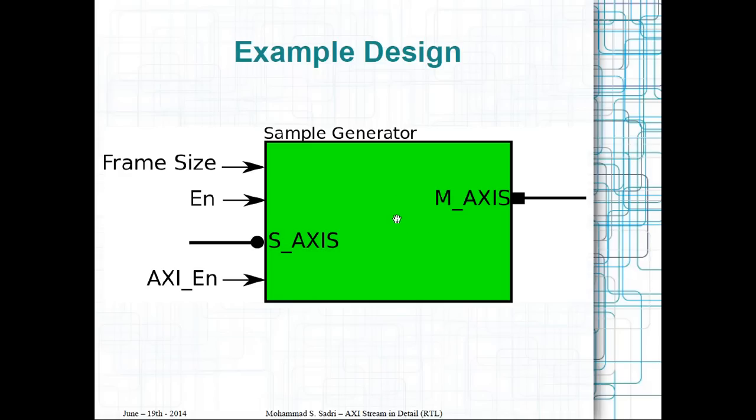first synthesize this block, because when you do an initial synthesis, usually it is useful because it shows you your major problems. For example, sometimes you do an initial synthesis and you see a large part of your circuit is optimized.